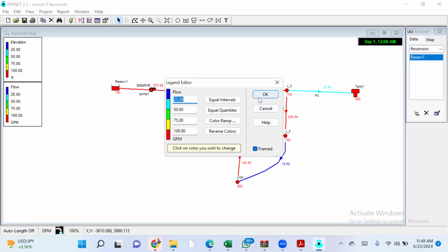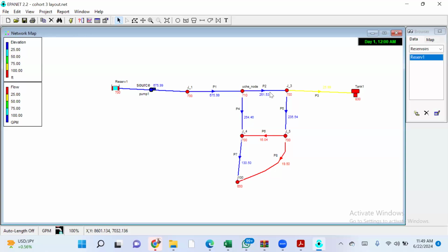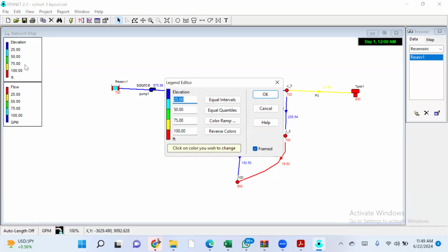So they're indicative of something. I can also reverse it, the other way around. Okay, I've reversed the color now. So it means high flow should be blue, low flow should be red. So with this, I can know where there are low flows in my network. Yes. The most important thing here is to learn how to right click on this legend and then indicate the upper limit and the highest upper limit. We're all engineers. Here you define so that when you plot this map, somebody from a glance can see where the problems are. That's the essence of computer.